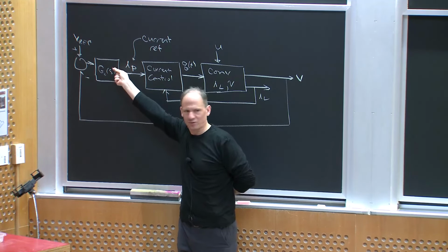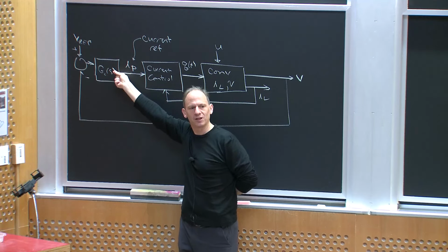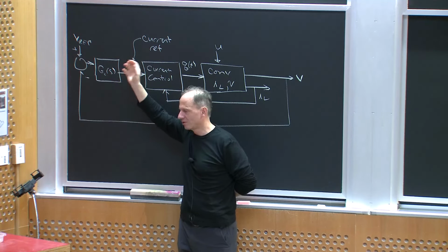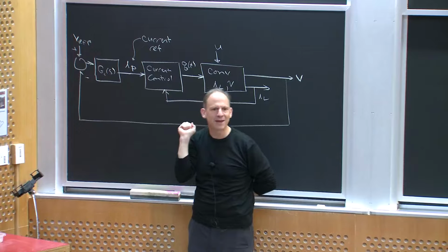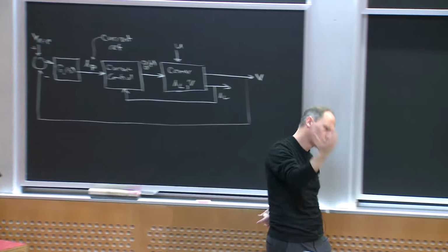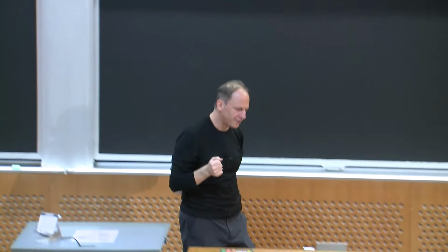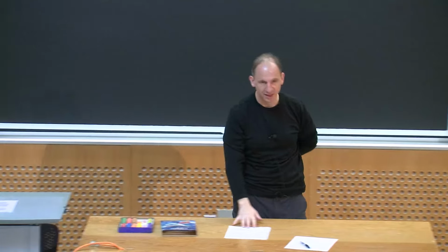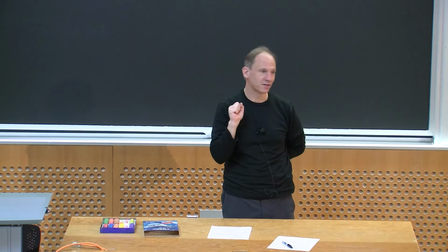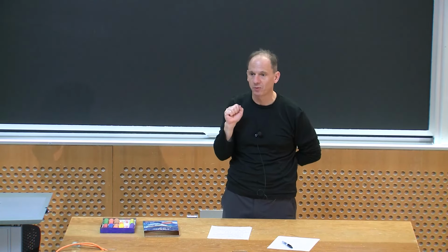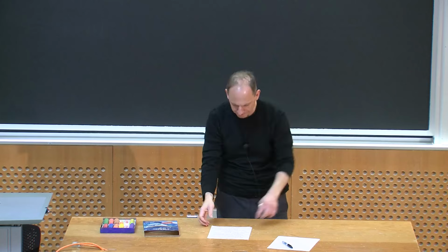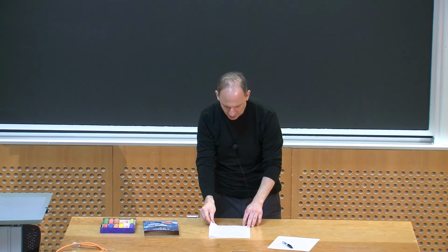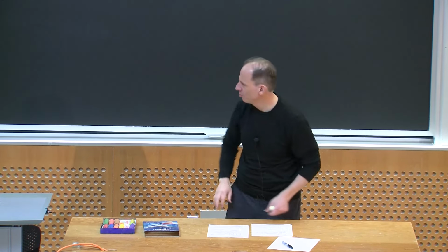The crudest way people like to think about this is I'm putting the inductor current inside a loop. So now I just get a sort of commandable current, and then I sort of have a first order system. Now it's not quite that good. That's an oversimplification. You still have two state variables, it's still a second order system, but it's not a bad way to think about it.